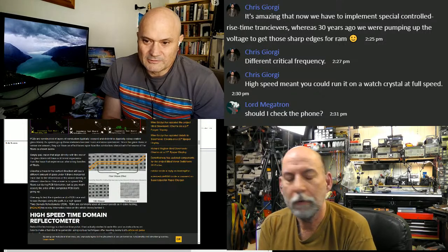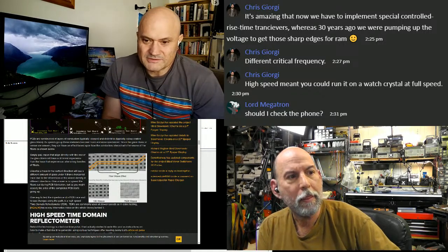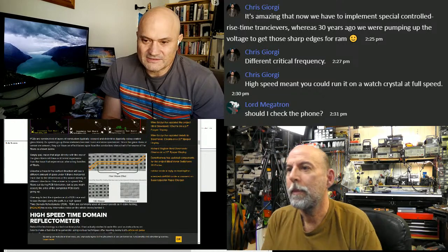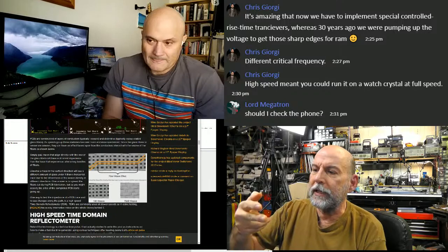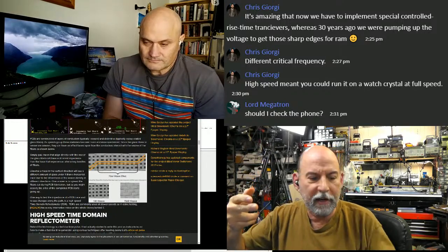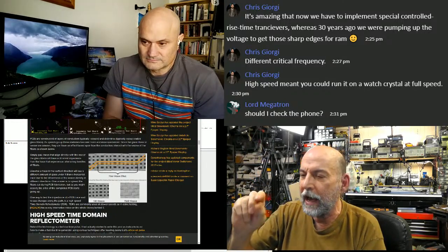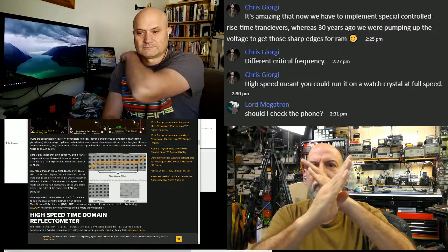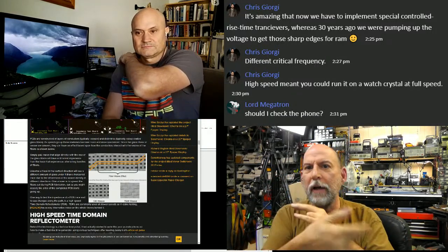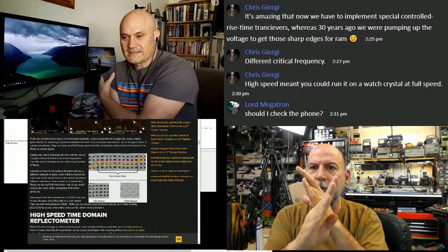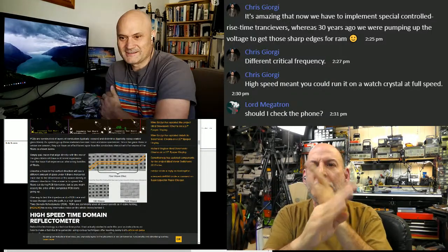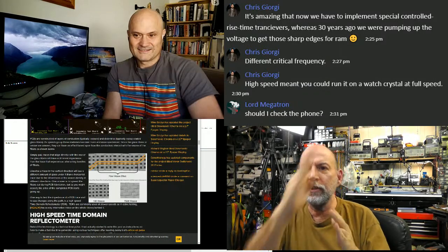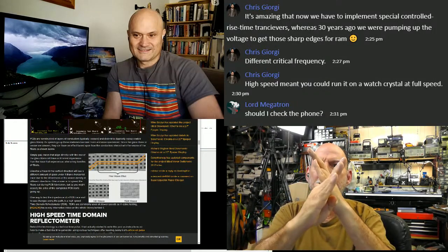Yeah, so that will delay, and really you want those two signals to be traveling together the whole way down the differential pair. Differential's not so much about canceling the voltage on both. In fact, the noise on both, if it happens right when they're crossing, and you may have seen eye diagrams. I call them cat's eyes for some reason, from the old tubes. But really, we're making edge detectors, and we want both edges to be the same.